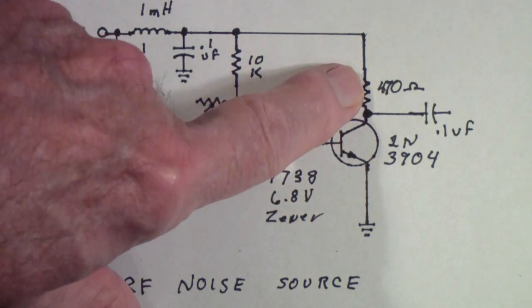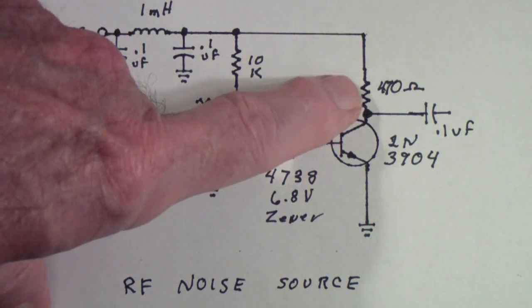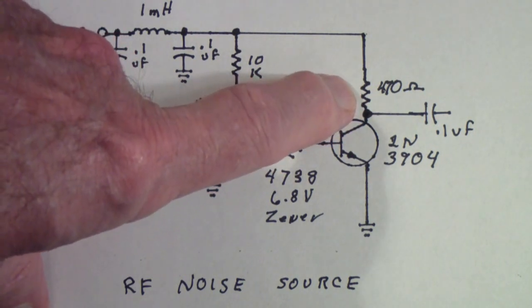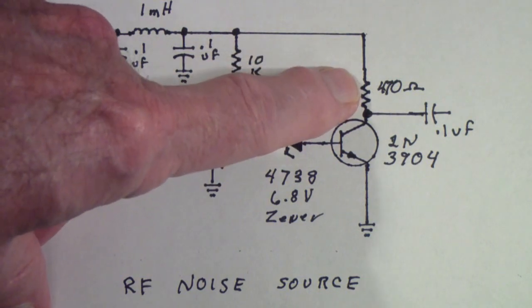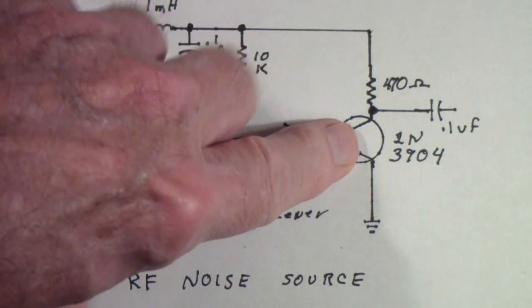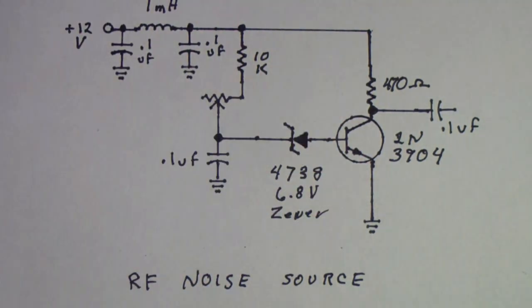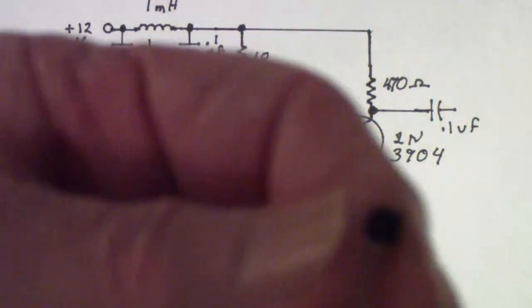The next thing is I tried some resistors varying this. I put a 470, which is the figure for the resistance of the circuit I got off the web. Then I went up to a 680 and finally to a 1K. And then finally I replaced the 3904 with a, see if I can read the number on it, S9018. Probably can't read that. Let's see if there's get a little more light up here.